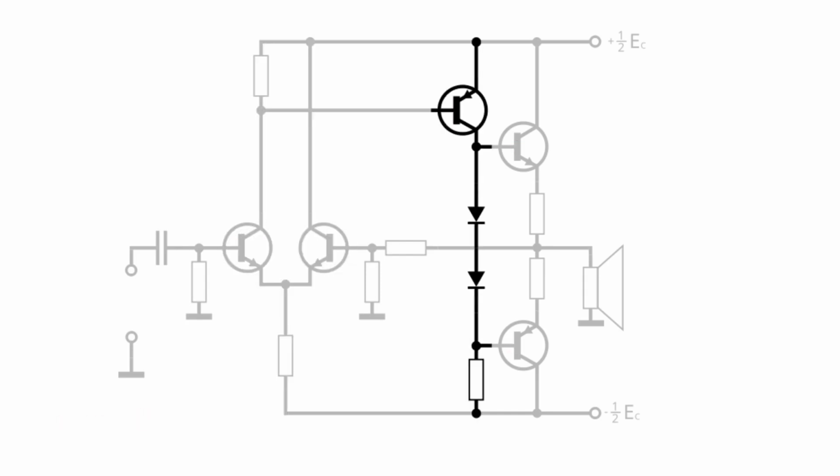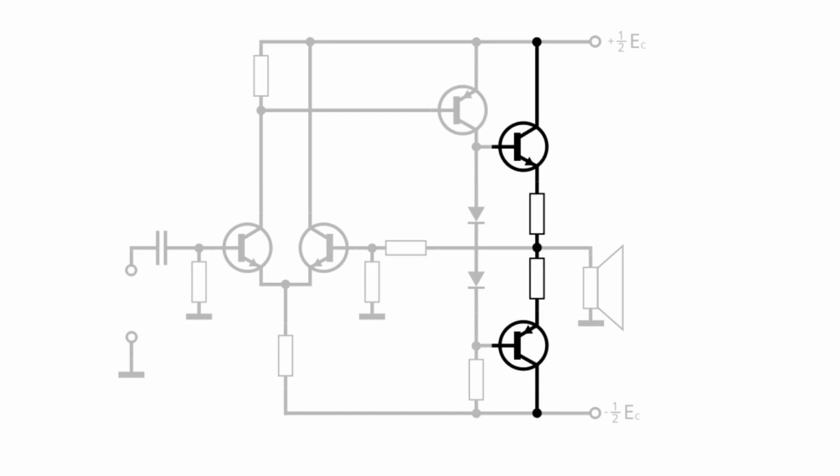The voltage amplifier stage comes next. Its primary function is to increase the voltage level of the signal received from the differential amplifier stage. This stage provides high voltage gain. Finally, the current amplifier stage. This stage is designed to increase the current capability of the amplified signal. This stage provides high output current, low output impedance, and is capable of driving low impedance loads such as speakers. This is the part of the whole power amplifier that adds power to the signal, as I mentioned before.